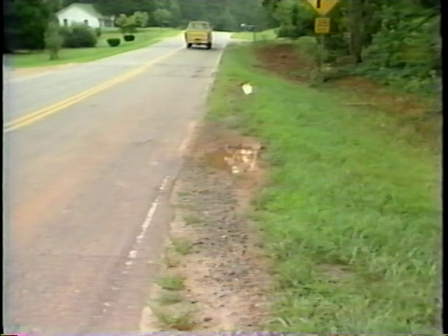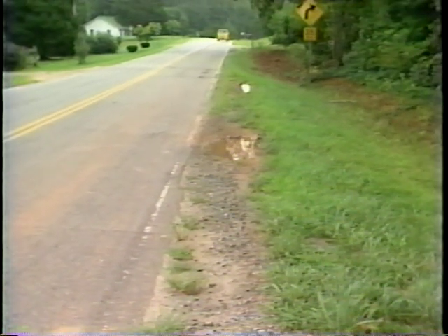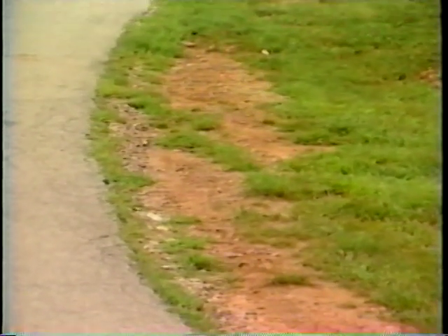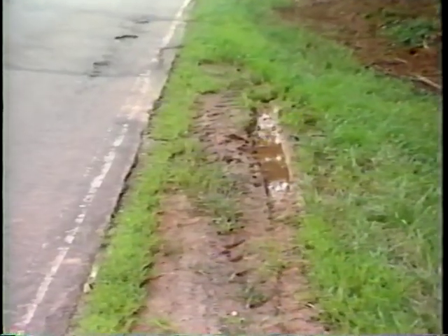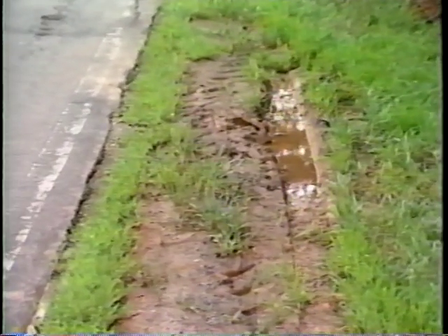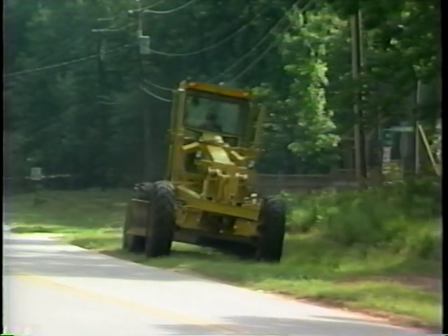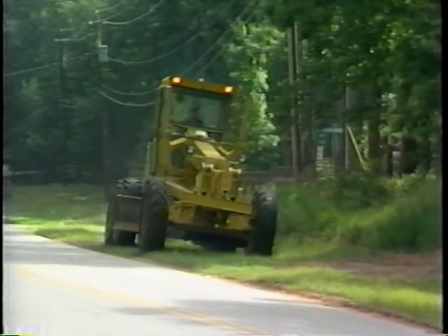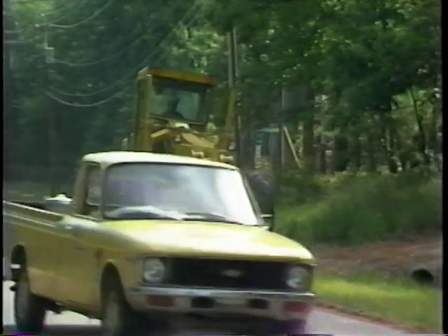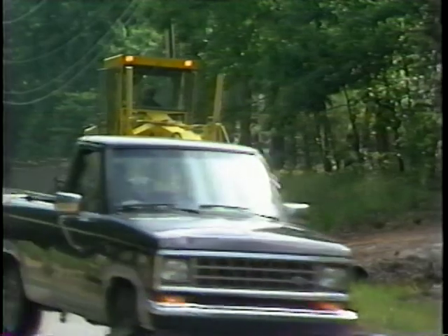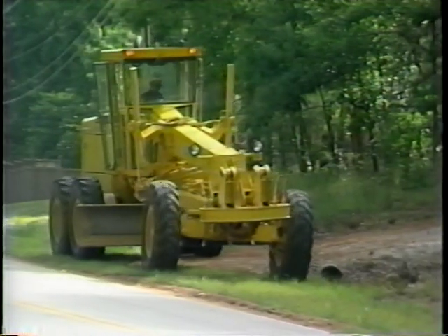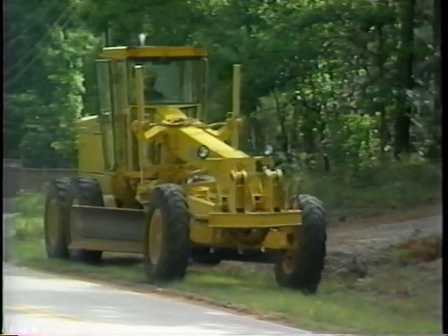Reshaping is required on an unpaved shoulder that has deep ruts in it. Reshaping is also needed to repair corrugations, ridges, build-ups, and areas that have eroded. In general, the shoulder is not smooth, and water cannot properly drain. A motor grader is the primary piece of equipment used in this operation. The motor grader can do an efficient job of reshaping the shoulder and eliminates the above problems.